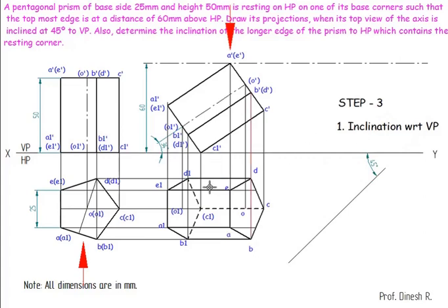Now I'm going to draw only the top face. I'm going to take this distance from C to D and C to B, which is equal to 21.86. So I'll go here with an arc. I'll take some point, making sure that the top view will not cross over the XY line.